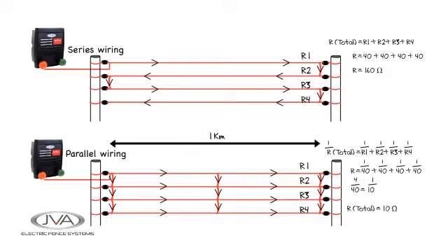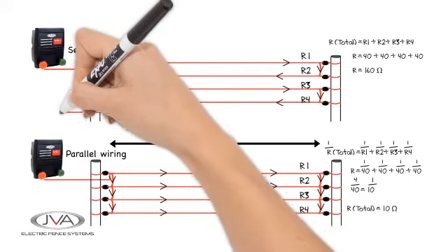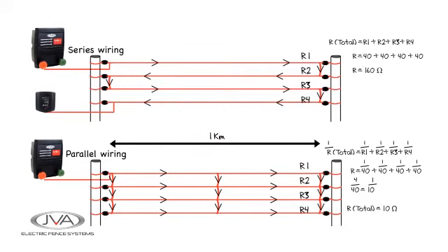So we can clearly see by the equation that a series wired fence will have a much higher resistance, and we cannot wire a long distance with it. It is perfect though for security fences, where we're fencing smaller properties, but require better sensitivity from the fence. When one wire is cut, the circuit is broken and we get a notification on the monitor.